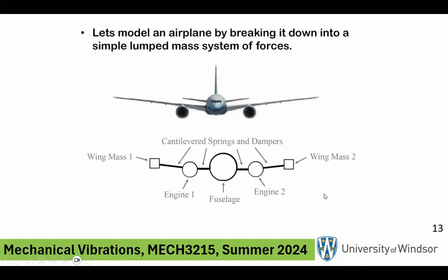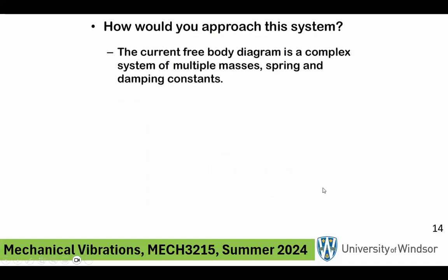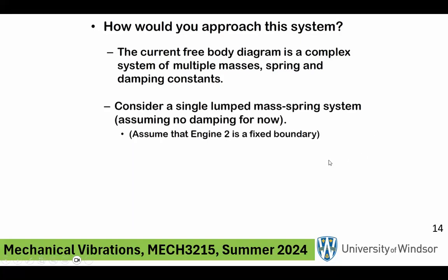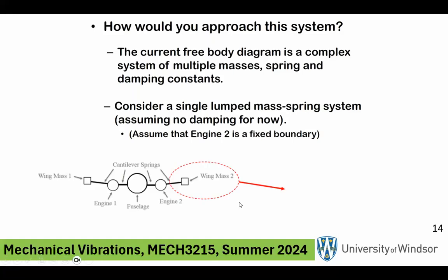So essentially, I can look at the motion of this engine in the middle, ignoring the stuff on the right-hand side of it, for example, as the motion of a mass and a spring. Right now, the way I drew it may be too complicated to look at. So what we are essentially doing is approximating that complicated setup with aircraft, engine, and wing as a simple mass and a spring. This becomes replacing the motion of the mass here as a single degree of freedom system. We'll come to those things later on in detail.